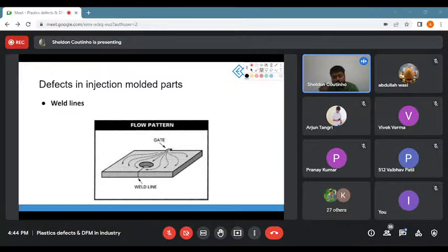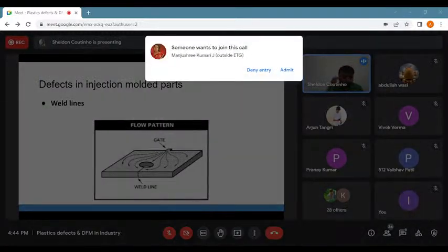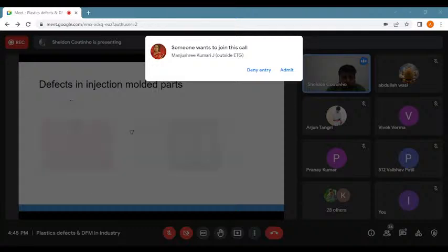One is to change the gate location. Second is keeping the mold warm. Both can be applied. Changing the gate location is much more preferred because you can keep the same rate of production. Always keep one thing in mind: you want to design something that has a really good rate of production. If the rate of production is lower, the number of manufactured parts will be much lesser. Any kind of failure, say during assembly, if your part breaks, the time of production also would get accounted over there. So that's why we need to ensure that parts are manufactured at a really great pace.